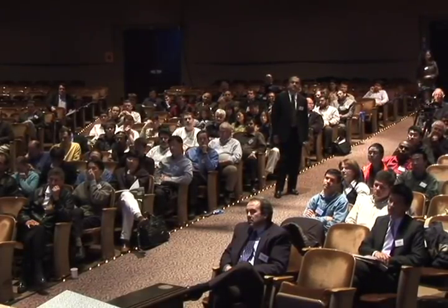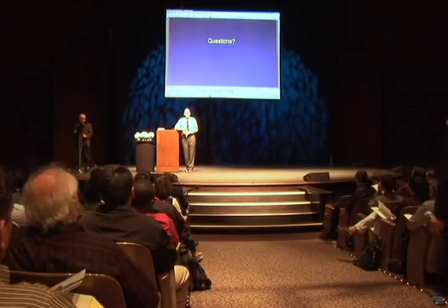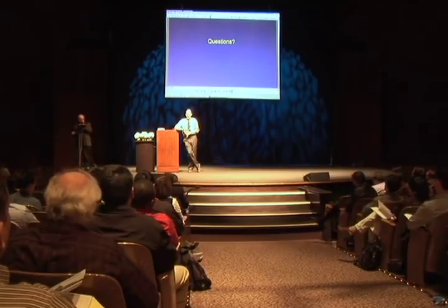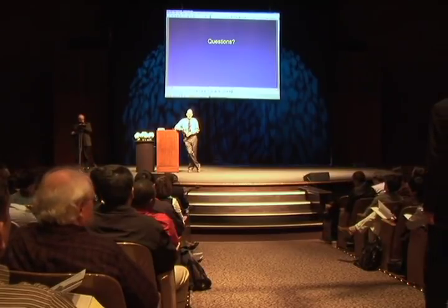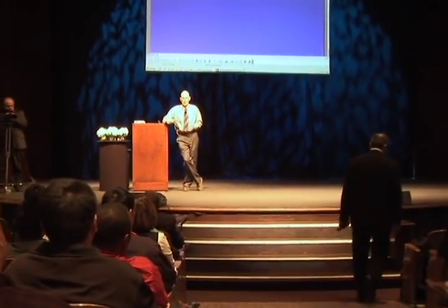A computer program like Perform 3D is just an analysis tool. It assumes that you have created your design and you want to assess the performance of that design. If your design is not okay, if it's either unconservative or maybe too conservative, it doesn't really give you any guidance on how you should change it. That's up to you as the engineer. And I would come back to the reasons I gave why capacity design is a good idea.